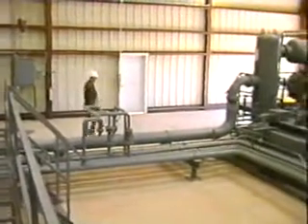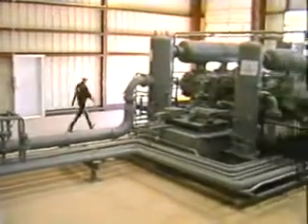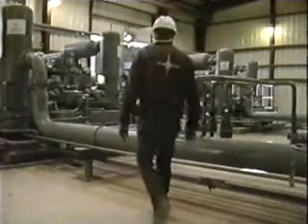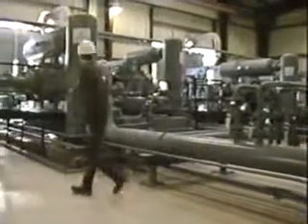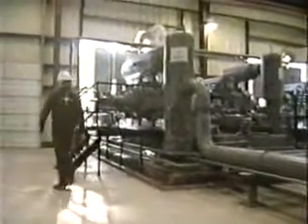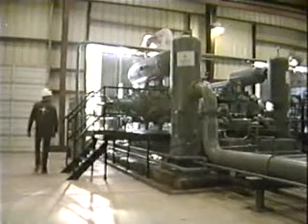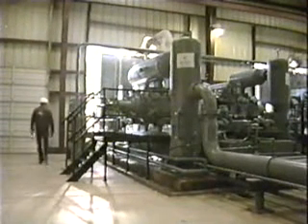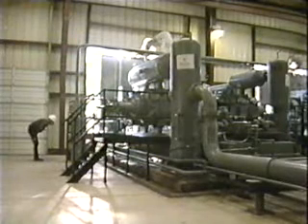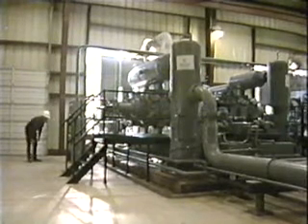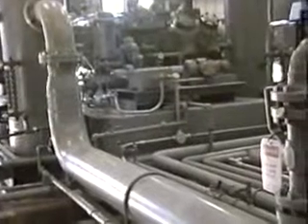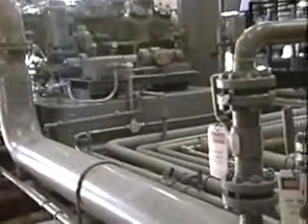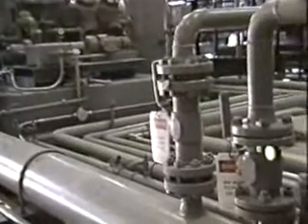Logically, the first place to check is the indicators to see if some malfunction has occurred. If so, the condition must be corrected before continuing. If, however, the shutdown was due to routine maintenance or an otherwise normal shutdown, you may continue with the startup procedure. The compressor loading sequence is determined by the presence or absence of a check valve.